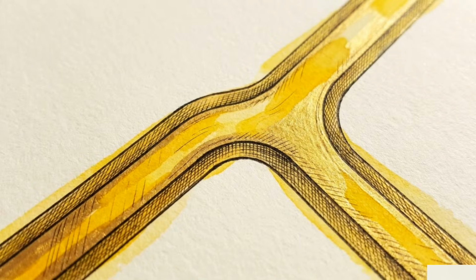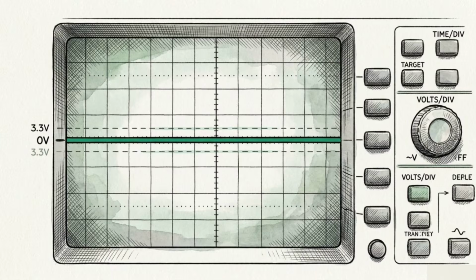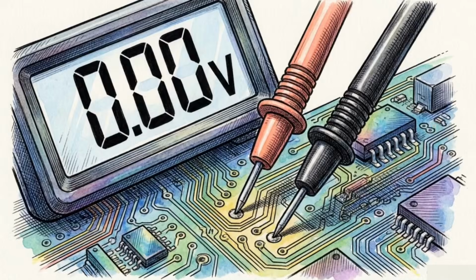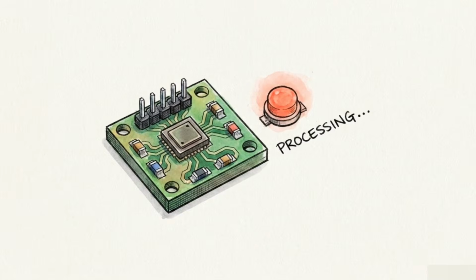This open drain architecture also solves data collisions naturally. Because devices can only pull a line to ground, a master transmitting a 0 will physically overpower a master attempting to let the line float high for a 1. The master sending the 1 monitors the bus voltage. It detects the unexpected low state, recognizes that it lost arbitration, and immediately halts its transmission to let the other master finish. I2C also allows a slave to control the flow of data.